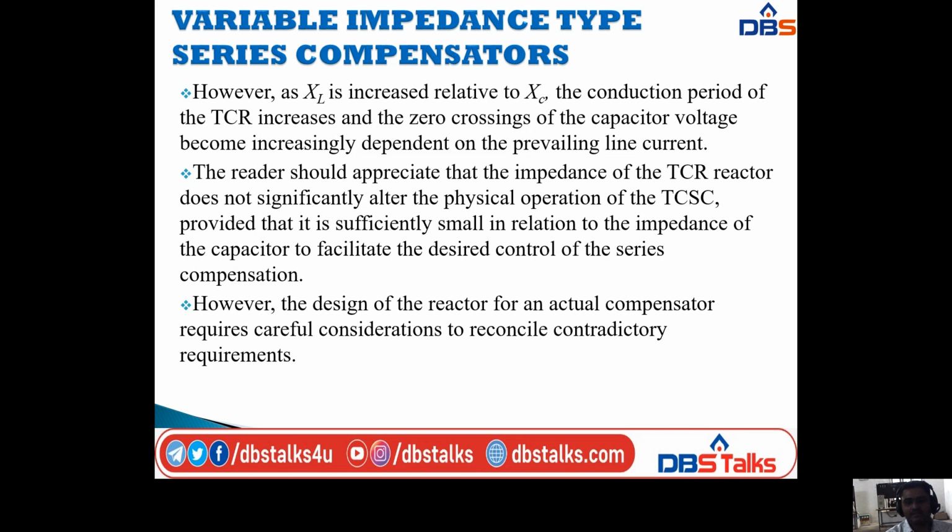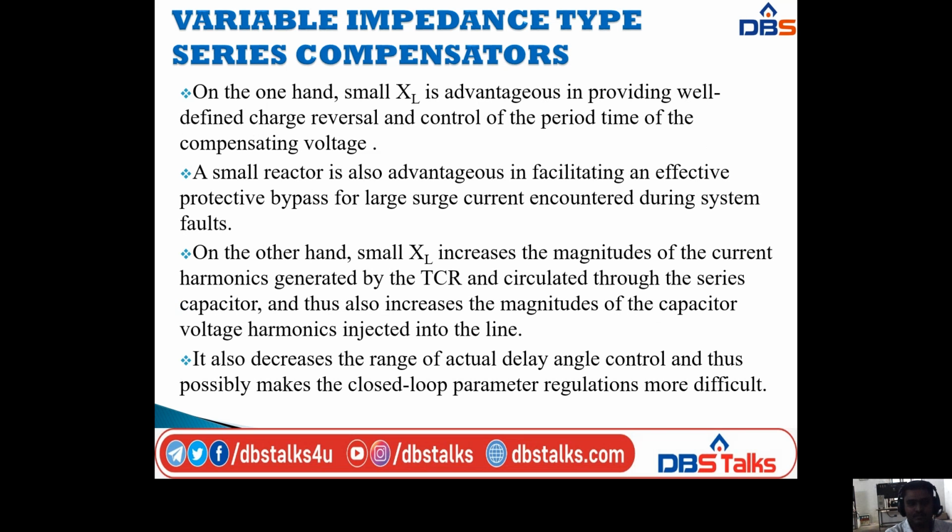However, the design of the reactor for an actual compensator requires careful consideration to reconcile contradictory requirements. On the one hand, a small XL is advantageous in providing well-defined charge reversal and control of the period time of the compensating voltage.